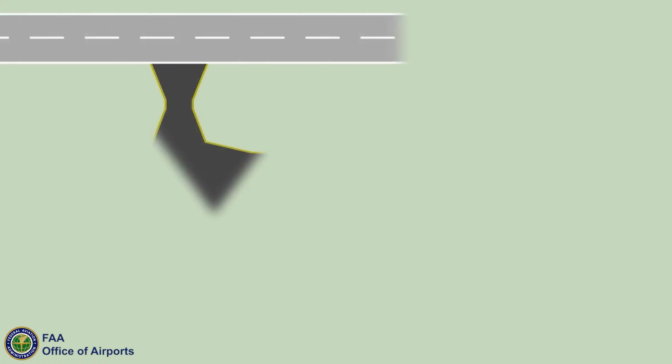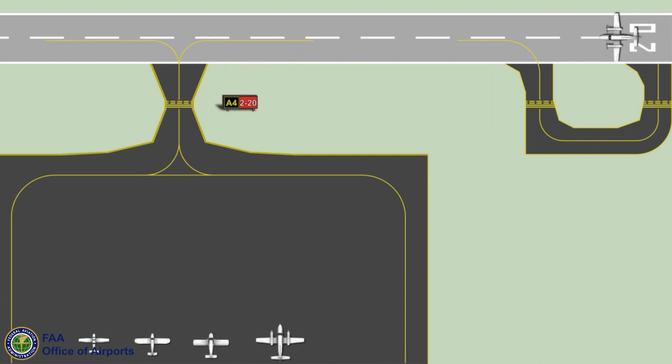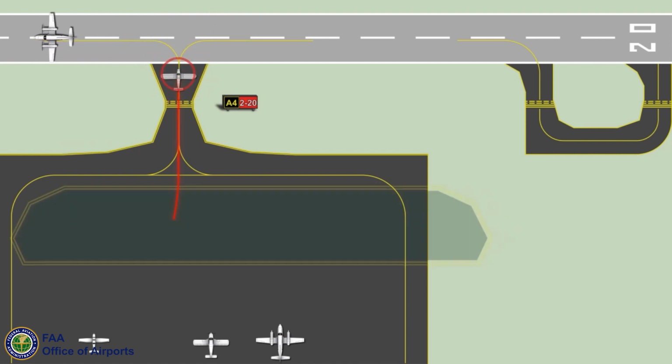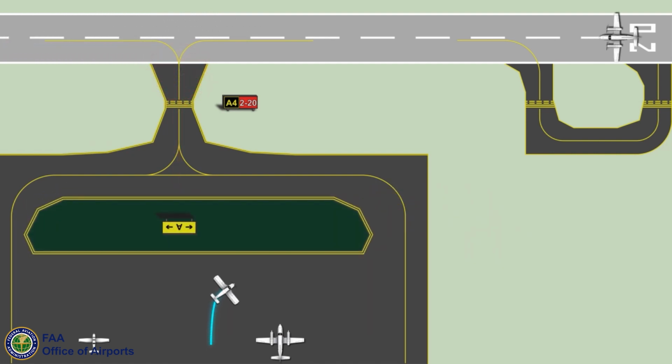Direct runway access is a similar runway incursion risk for airports that do not have a parallel taxiway. In this scenario, provide a no-taxi island on the apron to avoid direct runway access, forcing the pilot to make at least one turn before accessing the runway.